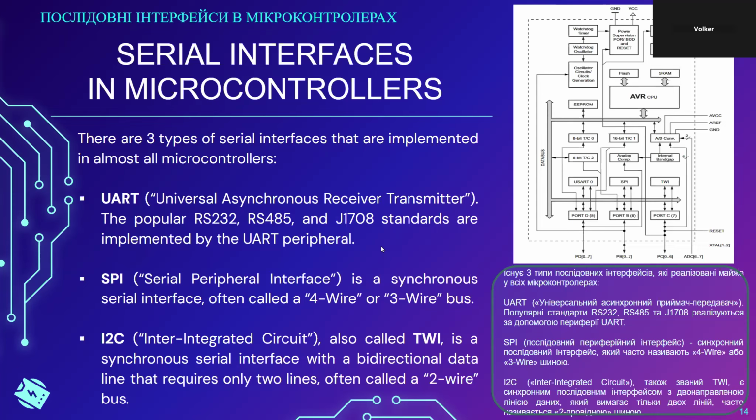There's a similar bus called SMBus, which is generally what you can find in PCs. It's like a minor control bus in PCs. It is not quite identical to I2C, but it is similar enough that most devices that work on a PC will work with an SMBus driver if you hook it up to an I2C device.